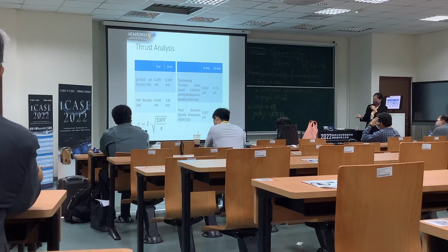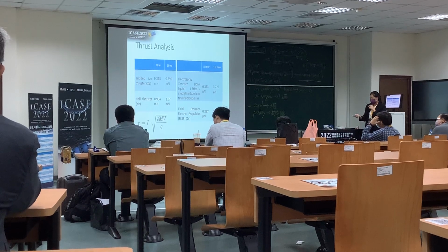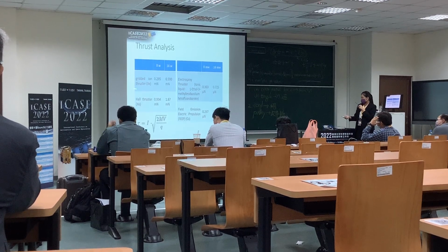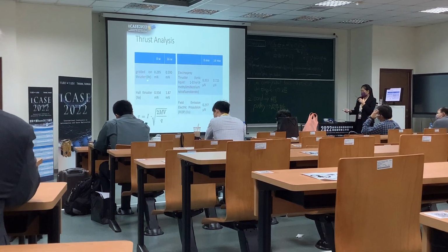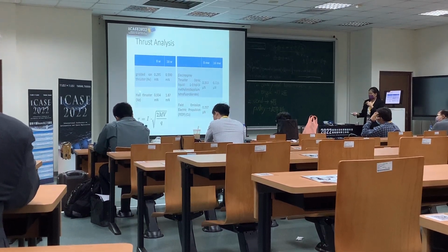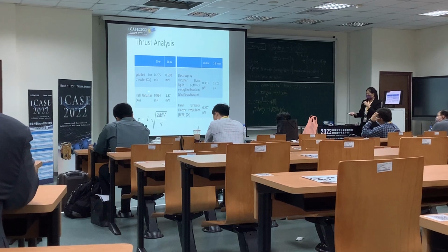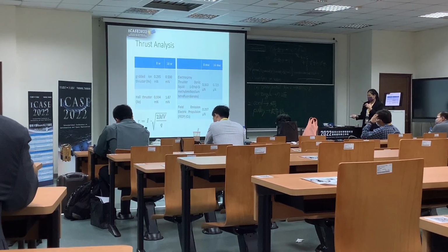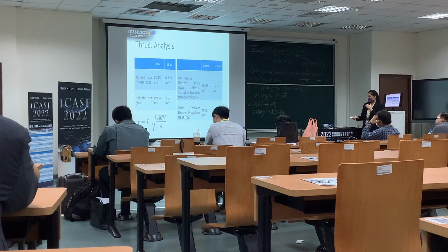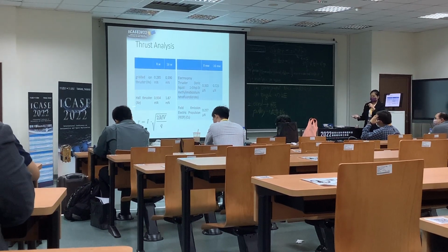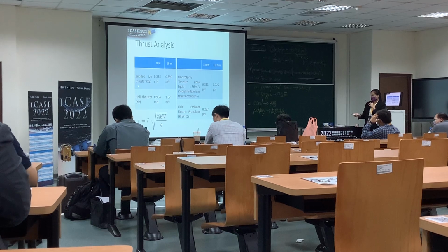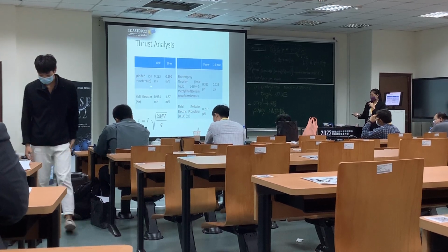This is the thrust analysis of electrostatic thrusters. We can see that those 2 thrusters that take all the energy generate different thrust. Why? Because even though they use the same type of propellant, they still differ in voltages and currents. Hall thrusters usually use a few hundred volts, while gridded ion thrusters use a few thousand volts.